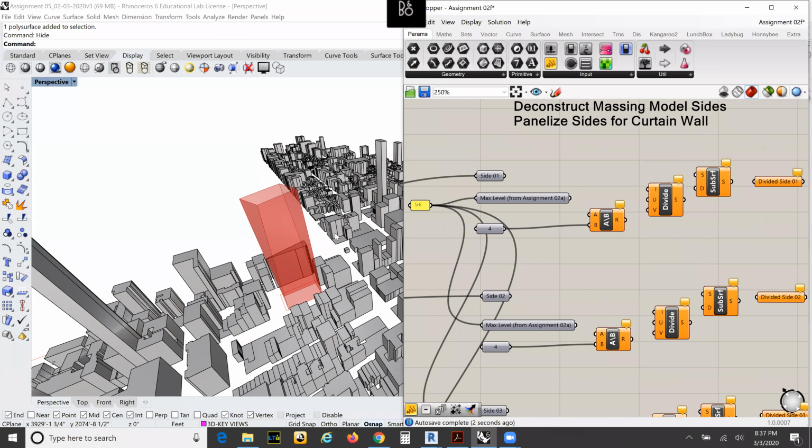And now we have to divide up this surface into 4 points. We actually want to panelize this surface, so that's the important thing, because we want to 3D model every single unique curtain wall on this face. That's why we're doing this. That's why we have an adaptive component that's made up of 4 points, because we're modeling this in detail, and we're going to have Revit recreate that for us. So that's why we're deconstructing this and breaking it down into pieces.